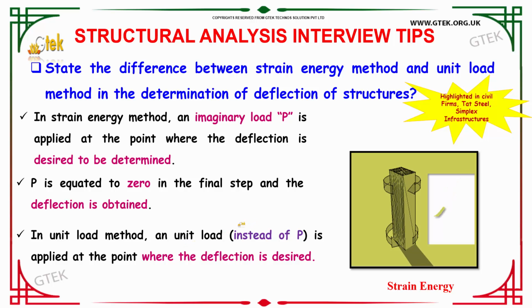In unit load method, a unit load instead of P is applied at the point where the deflection is desired. So by doing this, you can find the difference between the strain energy method and unit load method in determining the deflection of the structures.